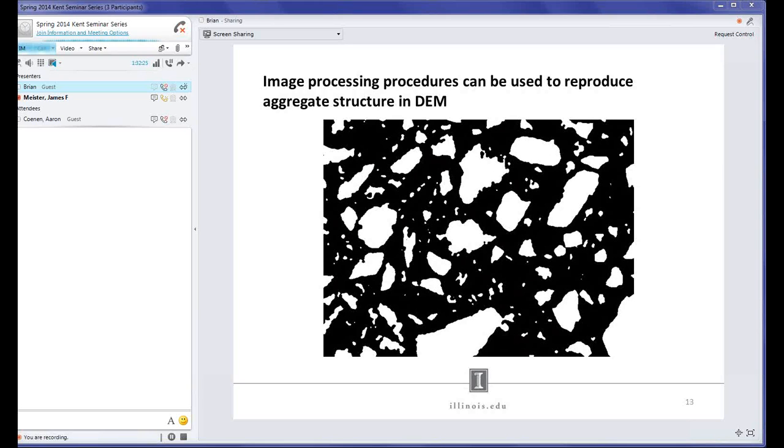I mean, it's watershed transformation. So, Mazir, I can talk to you about it later and give you a reference. I basically went through and adjusted based on the recommendations from Aaron's work that had been done at the University of Wisconsin. So I based it on that, and some of the verbiage I can't remember the exact names, but we adjusted based on that, and we also adjusted based on what aggregate we wanted to consider to be part of the mastic phase, because that changes.